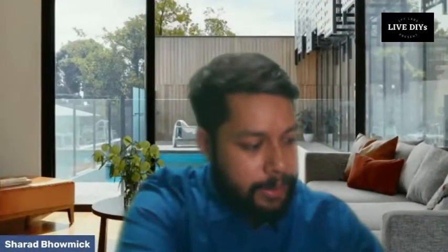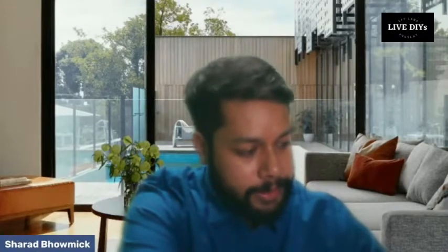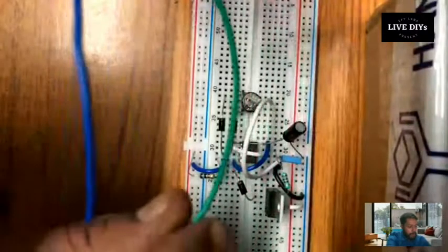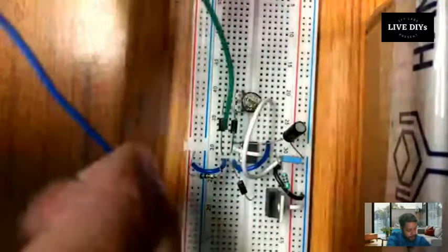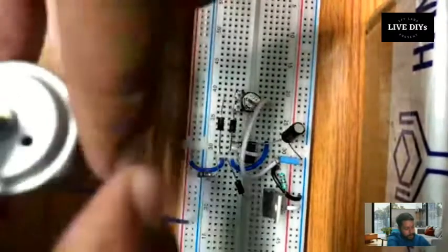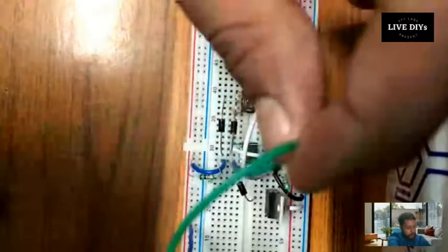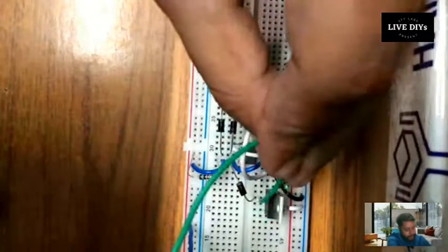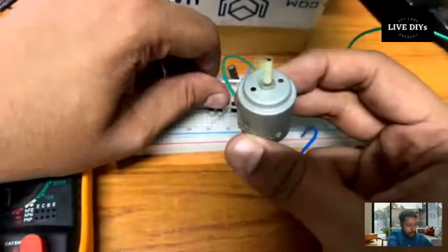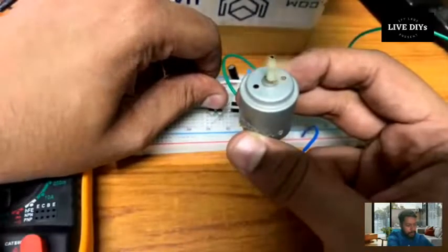I have the motor too, and I'll just first remove the LED strip. What I've done today is that I've used the blue wires for positive and green for ground or negative. So this is a positive rail where I'm inserting the blue wire. Hope you can see it clearly. And this is the negative, since we are connecting an N-channel MOSFET. Now, as you can see, the speed of the motor is controlled by rotating the knob. I'm trying to slow down the motor.